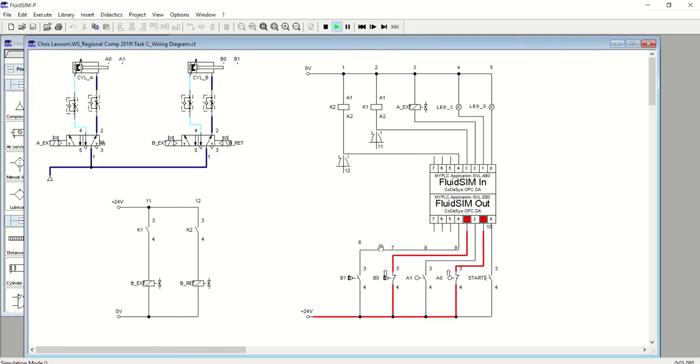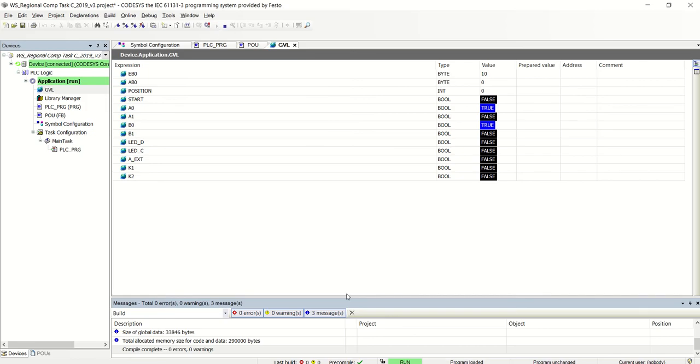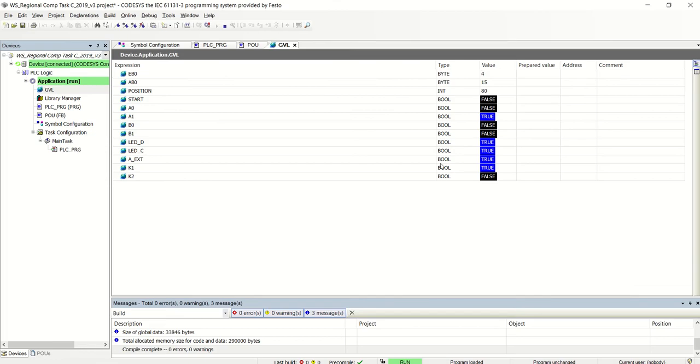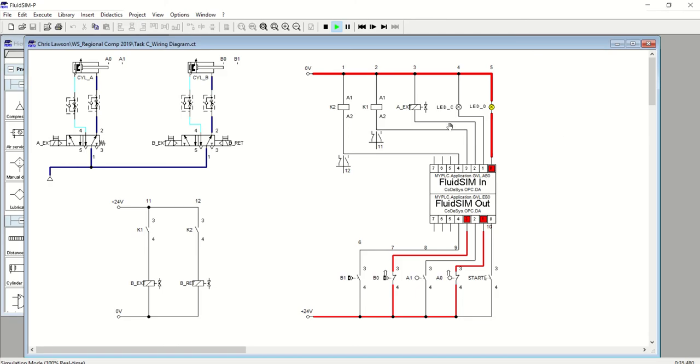So press play in the simulation. You'll see these two are starting in their retracted position. Then make sure that you've pressed play here, and you'll be able to literally press play. You'll see the 2 LEDs came on. This starts going through the sequence, so I can check, is that sequence correct? You'll also see if you go into Codesys, this all happened live. I can see I'm going through my steps there. Step 100, step 100, and oh, looks like it skipped maybe 110, 120. Maybe that just happened so quickly in terms of turning off the lights. So we'll double check it.